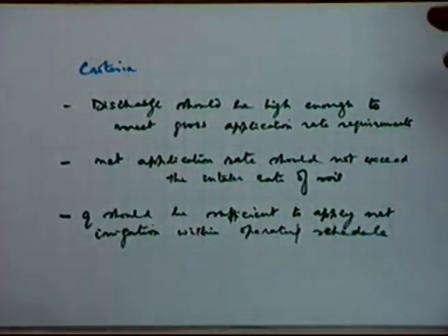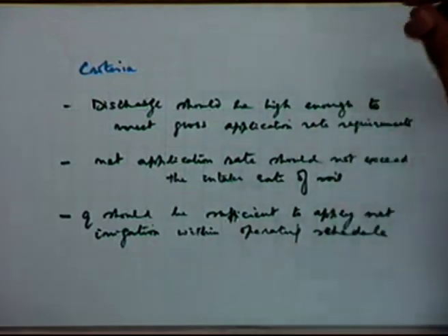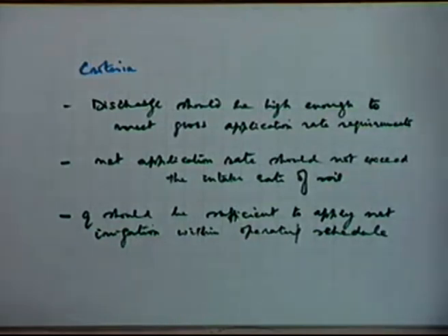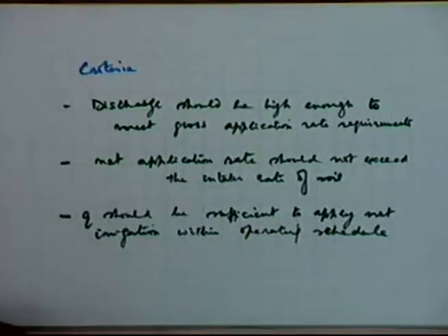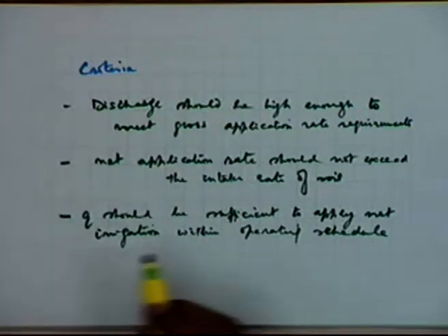Now you cannot select a nozzle size which has such a low discharge that the time taken exceeds the total irrigation in the total area under your interest. You exceed the irrigation interval. So that is another constraint put on the nozzle size, because the discharge will also be a function of the nozzle size, along with other things like the pressure, of course.